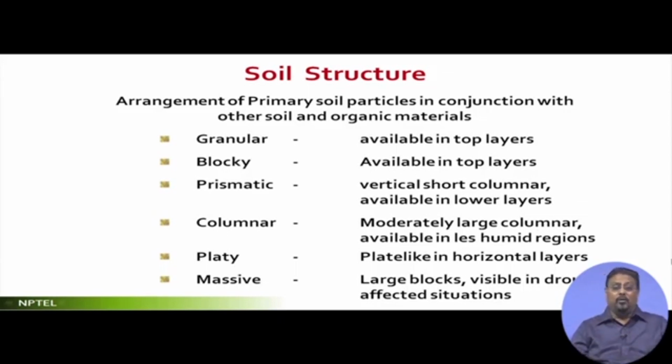If there are frequent landslides, then you also have to investigate why such landslides are occurring. It's mainly because the geomorphological character of that soil is micaceous rock, and mica as a soil material or mineral is very strong axially. If it is a plate and you put pressure, it will take axial forces, no problem. The moment you bring it vertically up, you will find that it will slide. It is structurally very weak when vertically placed, but the mica itself is formed in nature horizontally.